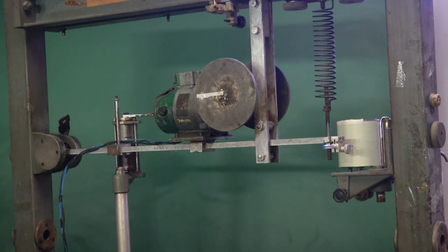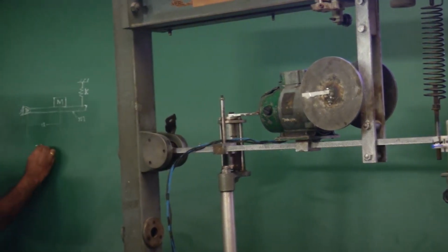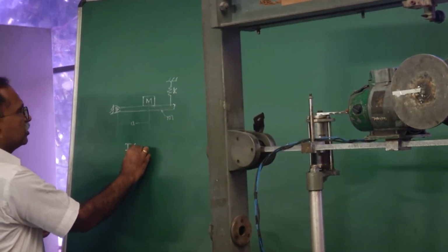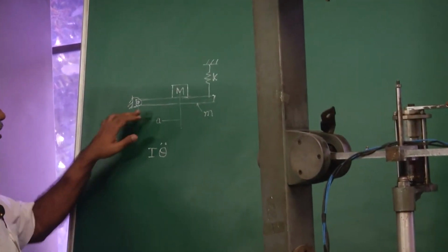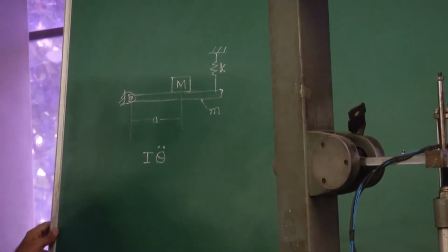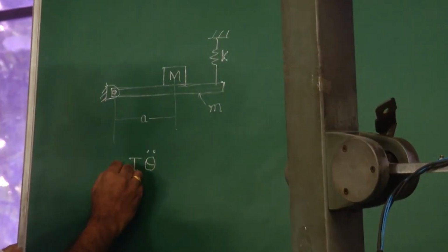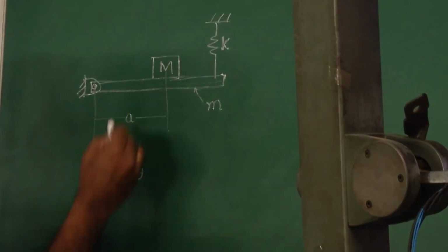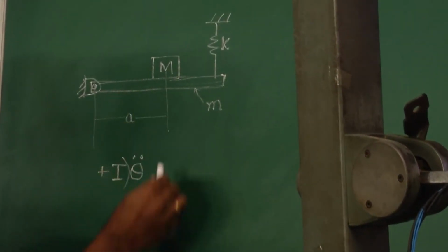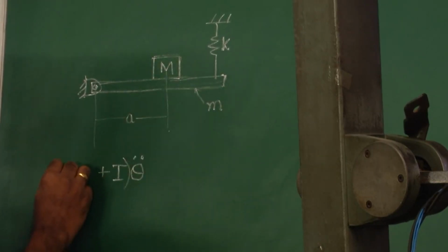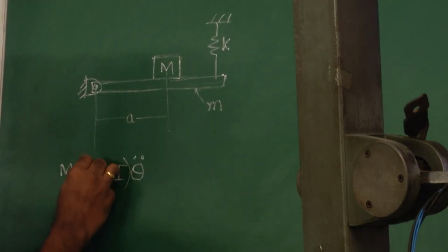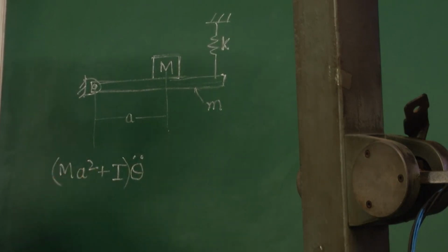Okay. So, then in that case, if I write the governing equation of motion as I theta double dot, which is going to be the value of I of this beam, and I can add to this mass moment of inertia of the beam the inertia because of the motor mass, and therefore, I can use m a square as the total inertia. Okay.